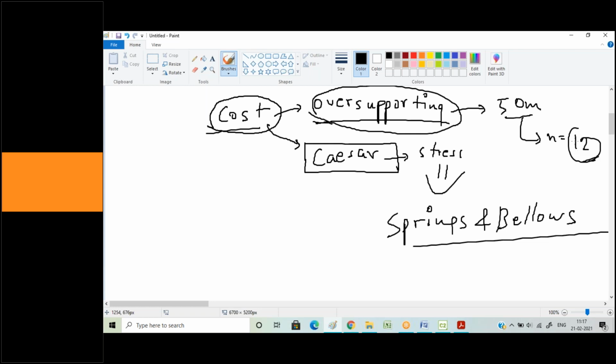Because obviously anybody who is giving any number of dead supports, anybody who is working on supports, has that much logic that he will assume a certain amount of load. Okay, fine, this is the amount of sustained load. So anybody doing the basic supporting on piping keeps that sustained load in mind, that this particular support, say my two supports, can support a span length of 4 meters, depending on the size of pipe I'm dealing with. Say if it's a larger size, obviously your span will tend to decrease.